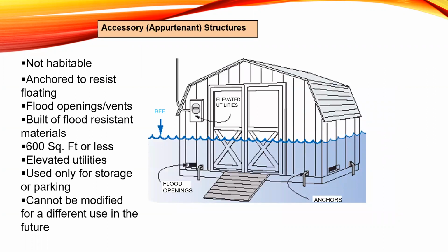Okay, so aside from enclosures underneath residential structures, the other two things that we can wet flood proof are pretty common. I get questions about these all the time. Every time we do an audit, there's several accessory structures that have gone in unpermitted. So they pop up all the time in the floodplain. People might not realize that they need separate permits, and so doing outreach can help.